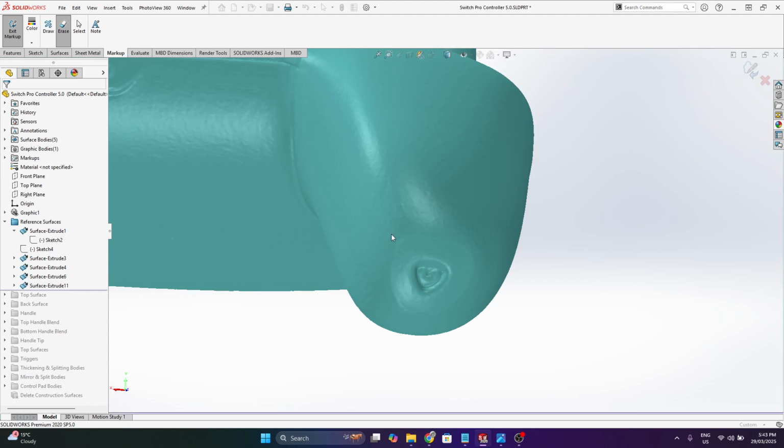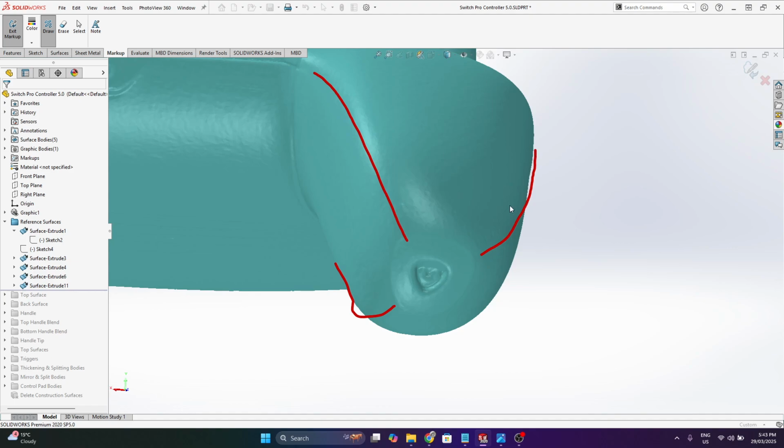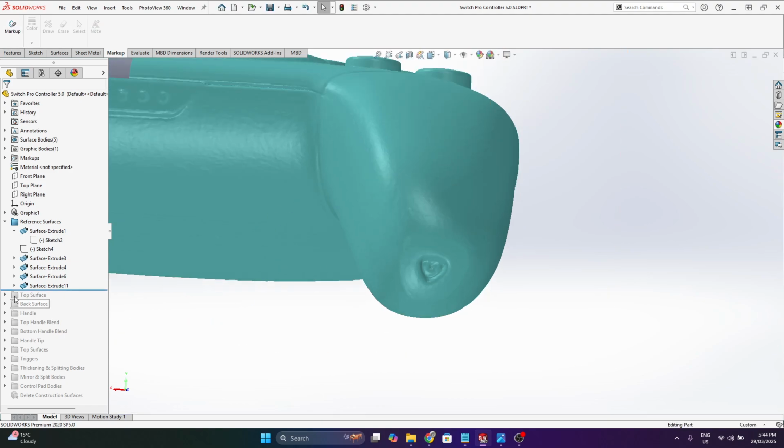What I mean by that is there was a parting line along here, a parting line that way, and then a parting line up here, and then a central section there, which just means these three sections would have moved out after this was molded. Just good to have an understanding of how this may have been manufactured as you're going along.